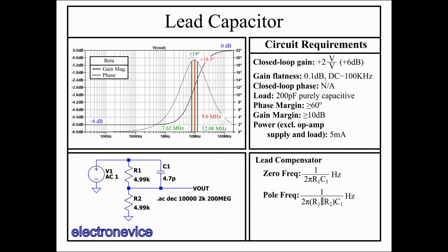We'll note that this actually changes the closed-loop gain function of our system and makes it unity rather than a gain of 2 at high frequencies when the capacitor is shorted. However, this only comes into effect when the loop gain is already near unity, and so the ideal gain is already collapsing. Furthermore, it doesn't violate the gain requirements within our required bandwidth of 100 kHz.